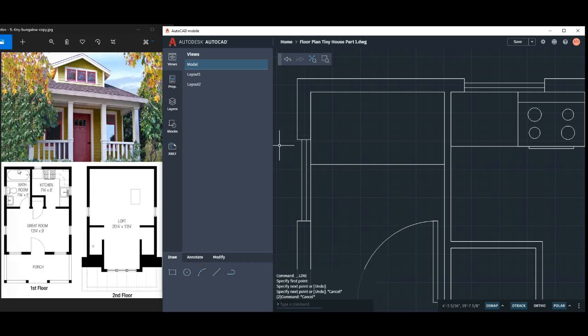So there's this rounded tub shape inside here that we have to create. There's always a couple ways that you can accomplish the same thing in AutoCAD. So you could just use circles and then lines attached and get rid of partial circles. I'm just going to use a rectangle, and I'm going to round the corners with the fillet tool that we used the other day there.